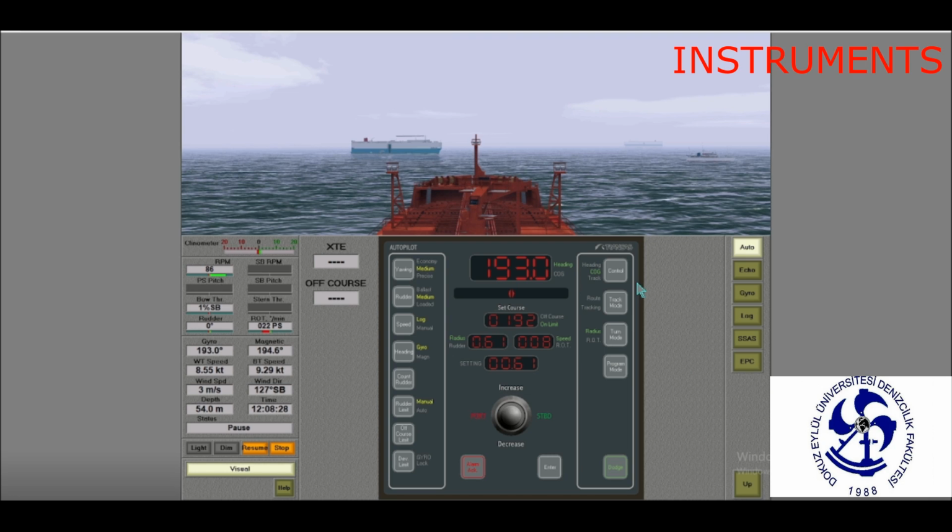In course control mode, the course over ground is steered along. Data is supplied by the GPS. The ship's drift is taken into account. Track mode is the key for selecting the mode of steering the ship on the route. Route is control of the motion along the route implemented in the autopilot. Tracking is the control of motion along the route from an external track control device.